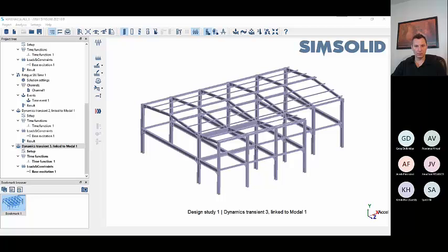I'm embarrassed to say that I don't know much about dynamic transient analysis. Usually, in traditional FEA, the base excitation would have gone where you put your boundary conditions to restrain the model, sort of at the base, because it's a base excitation. So what happens is you wiggle the bottom, and then the rest of the structure wobbles in accordance, right?